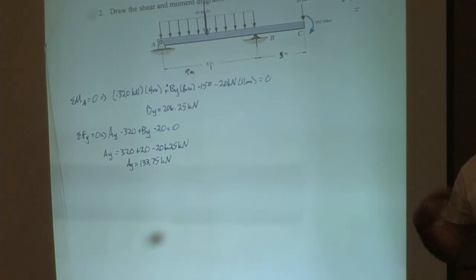If you want, you can ask me after class about the method of integrals for any of this stuff, and I can try to show you quickly. But the key to the integrals is you got to practice, because you have to solve for C. And initially, if you're starting out on the shear and moment diagram, C is easy because C is 0. But if you do it midway, you got to solve for the C. So I can show you how to do that afterwards if you want, but I can't do it during the presentation, I'm sorry.